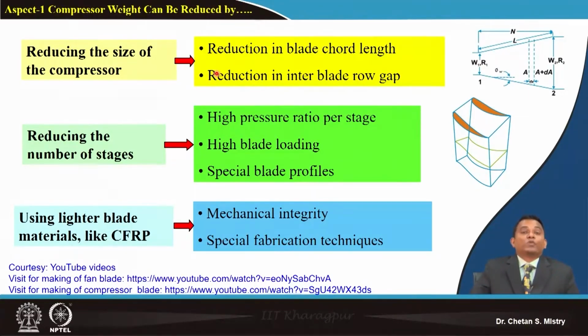Those two absolute velocities are the same, and we are assuming those absolute flow angles to be the same. If you put this gap too large, that may not be valid, and my stator may go under off-design condition, or maybe it will reduce my operating range. So this is one of the challenges.